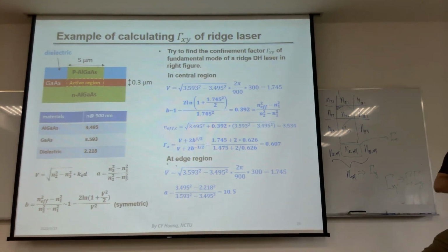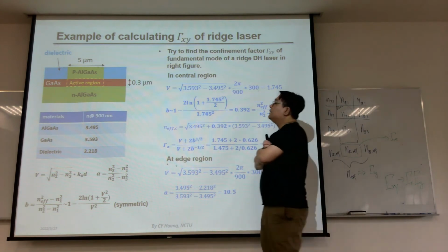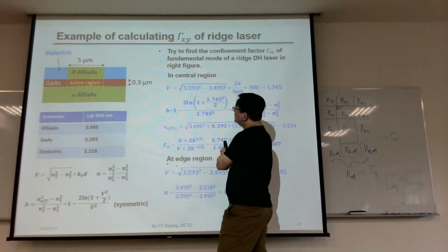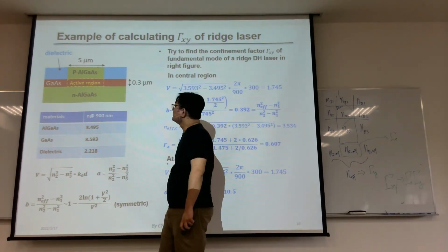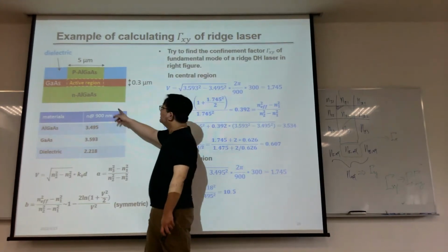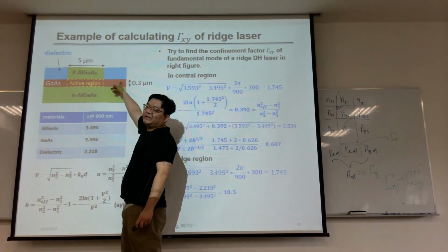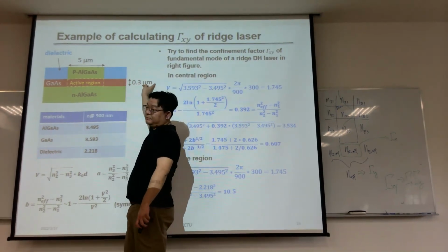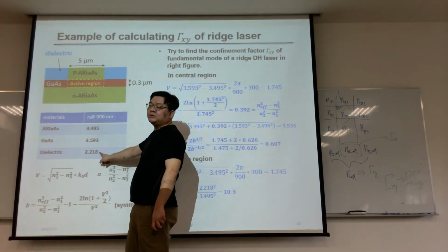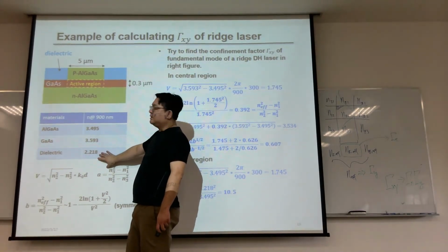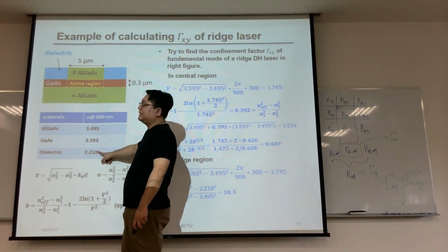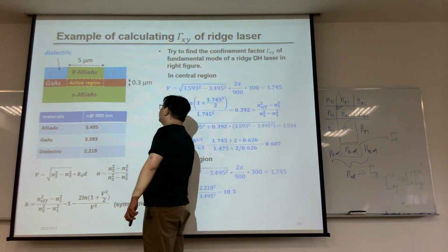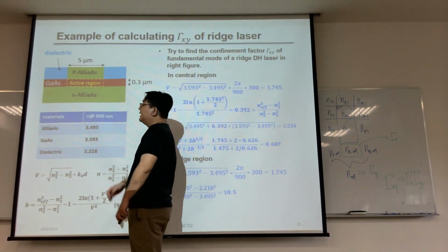So let's try a real example. Okay, so let's consider a GaAs-InGaAs structure. And the P-GaAs is etched and deposited with some dielectric, with a much lower refractive index, because that's what really happens. A refractive index of 3.5 is actually pretty high. So for a common dielectric, the dielectric constant is usually much smaller. The refractive index is much smaller than gallium arsenide.